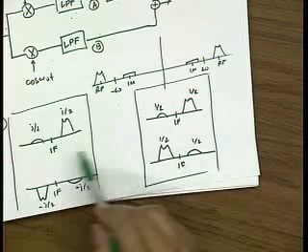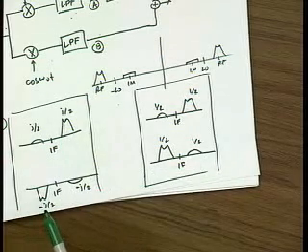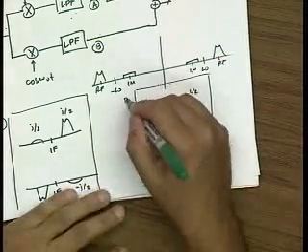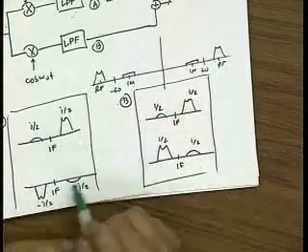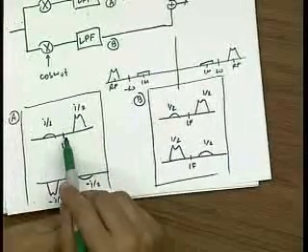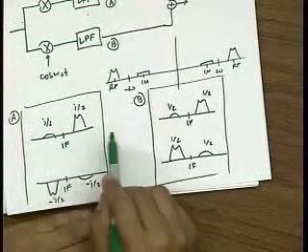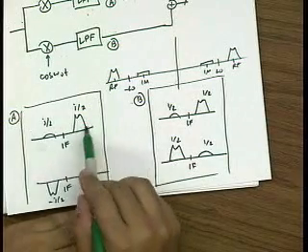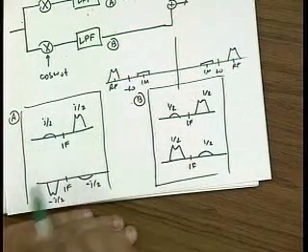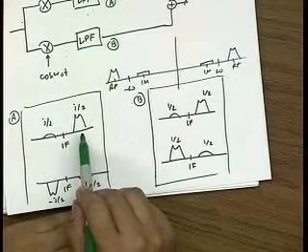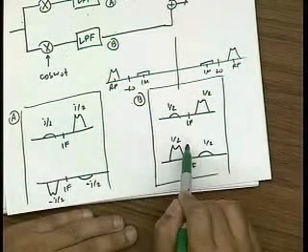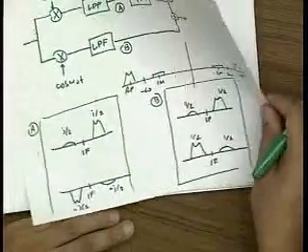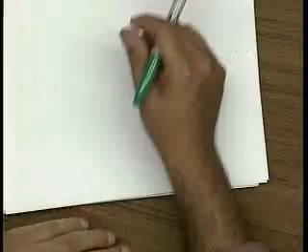You can see if I sum these directly, the signals will cancel out. On the other hand, if I put a phase delay on A, remember, the phase delay affects the negative frequencies differently from the positive frequencies. So it multiplies by plus j in the negative frequencies and minus j in the positive frequencies. So that would actually flip things around in a way that would make things favorable. So let me show what happens when I flip things around.